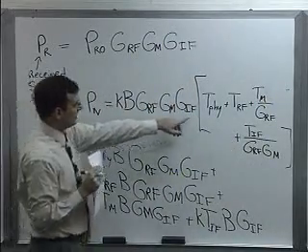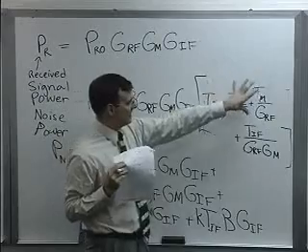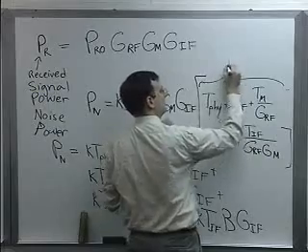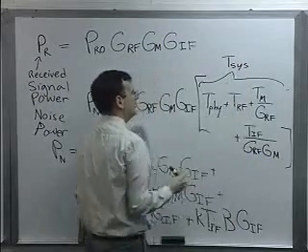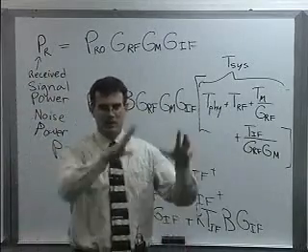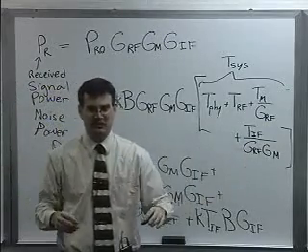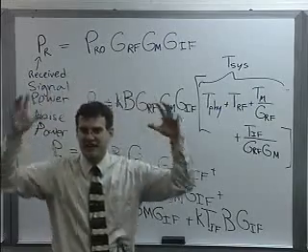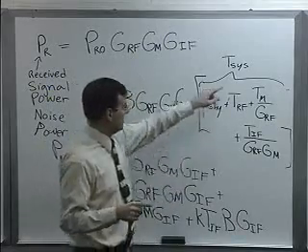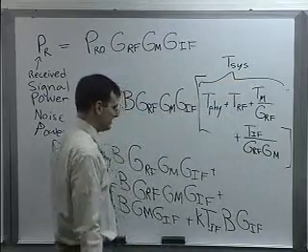Okay, so look at what's happening here. First of all, I have something in here that has units of temperature. All this stuff together is actually what we call the physical temperature of the system, T sub sys. A temperature in kelvins that collectively represents how the entire system, my antenna, my amplifiers, my oscillators, my mixers, whatever device is interacting with my RF chain, how that effectively adds noise to your system. So a lot of times when you're speccing out a receiver for communications, this is one of the most critical components that you want to read off of it. What is the T sub sys?